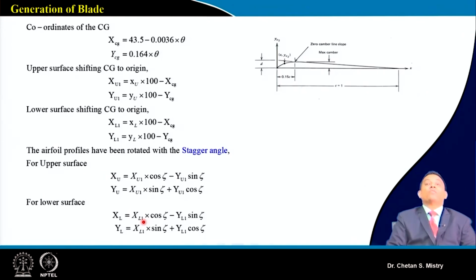When we are looking for this curve to be smooth, we need to have more points. So decide on more than 500 points for the upper surface, and the same way more than 500 points for the lower surface. That will give you continuous curvature without zigzag. I'm sure you can do this programming for making this blade.